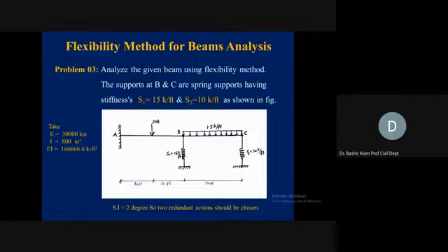What happens now in case, let's say you are using a penthouse on the roof, you are now installing a generator. So if you put this against a rigid surface, what will happen? It will cause vibration in the floor now. Now, to eliminate or to minimize those vibrations, what we do, we usually put springs. Sometimes people, if springs are not available, they put tires under the generator just to minimize those vibrational effects.